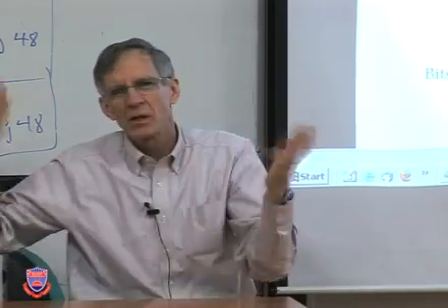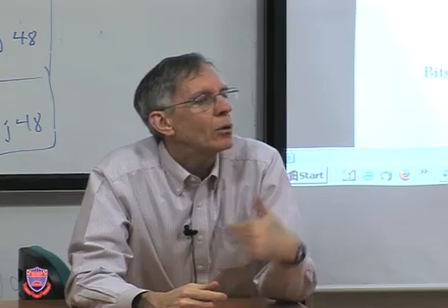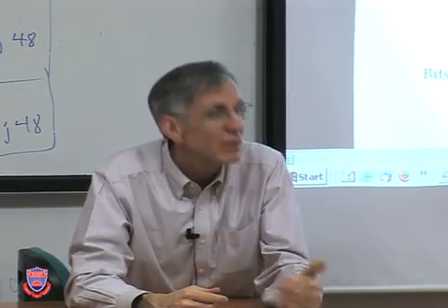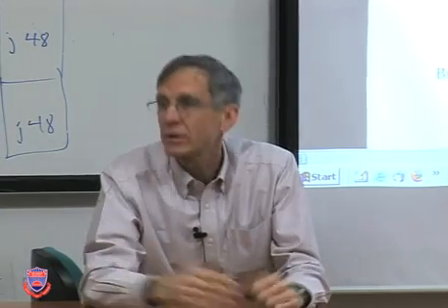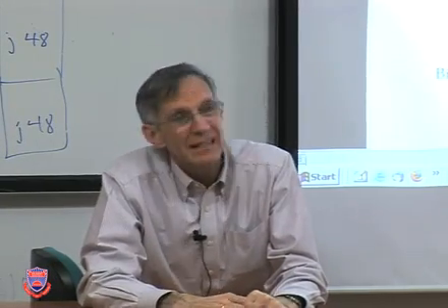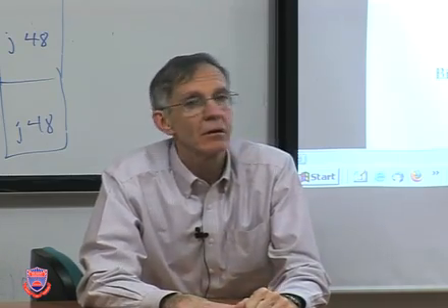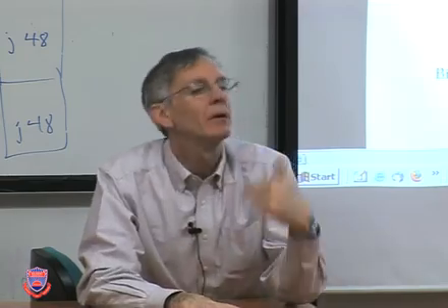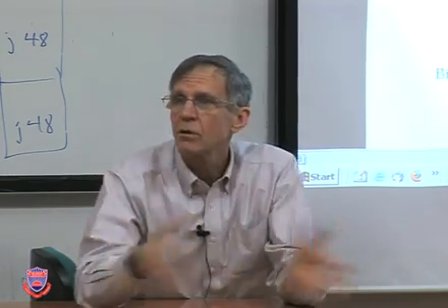At first I misunderstood what your confusion was. In the end, now I know what you know. He was asking, how do we address where we want to go to if it's branch? Answer, PC relative. How do we address where we want to go to if it's jump? Answer, pseudo direct. How do we address the data we want to go get if it's immediate addressing? Immediate. If it's a load or store, base plus displacement addressing. If it's an R-type, register addressing. There we go, 5 addressing modes. Good review over the ISA.